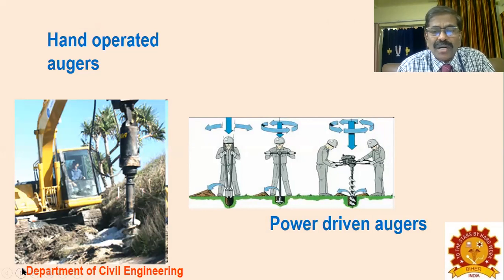It is something like drilling. Just like your drilling machine, it is a very big size for rock drilling, or very big size for soil drilling. That's all. It may be hand operated as in the case of figure 2. In figure 1, you can see an auger bore well, and it is machine operated. It is operated with compressor tools, where high pressure is used for auger drilling, as well as some motorized mechanisms. You can see an auger boring here. You can see a manual auger boring also here.